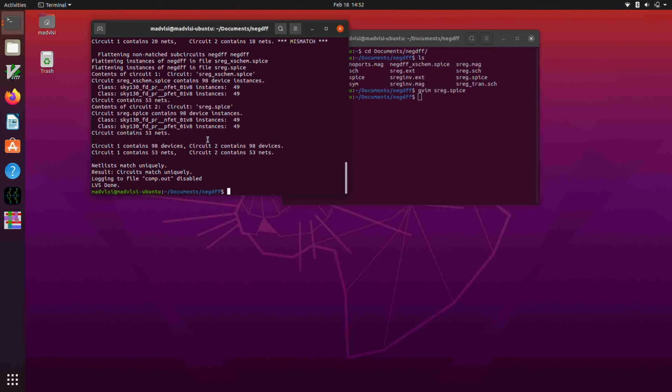It was hard enough to figure out what it was in the last video with just one cell. If you imagine having 98 transistors and whatnot instead of 24, it could be quite a lot harder to figure out what things were going wrong if they hadn't matched. So I always recommend that you do LVS incrementally as you go as a good practice. Okay, so that's constructing the shift register in Magic and doing LVS on the shift register.